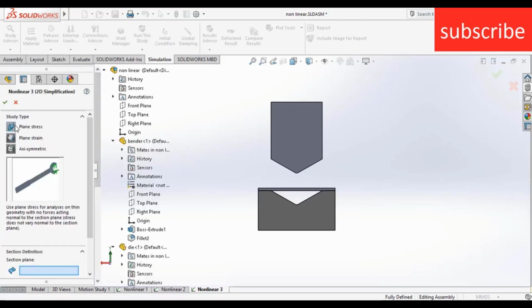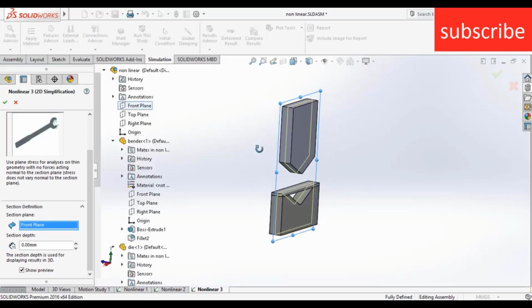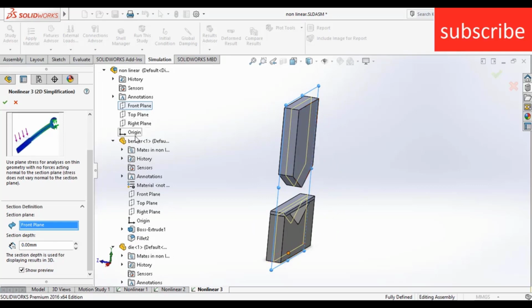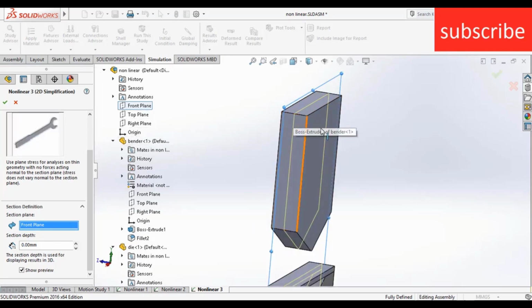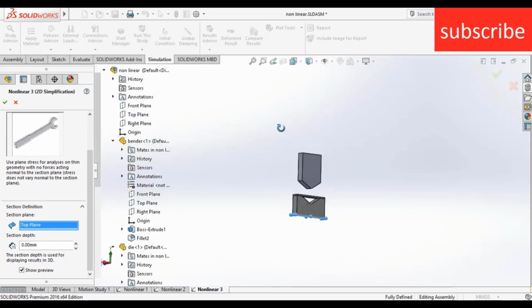After that, it is asking me to select the plane. As you can see, it says selection of plane. So basically a question arises in your mind, what is meant by selection of plane and depth. Here I am choosing the front plane. Why the front plane? Why not the right plane? Why not the top plane? I am choosing the front plane because with respect to the front plane there is total symmetry of my drawing. If I choose the top plane, there is no symmetry. Let me show you. Here for example, I choose the top plane.